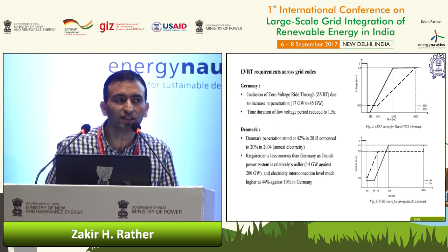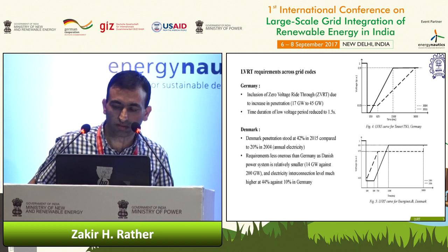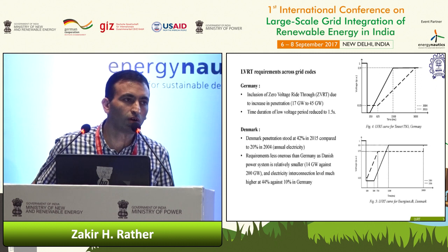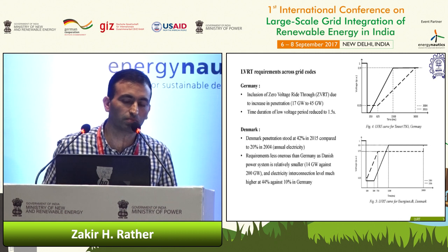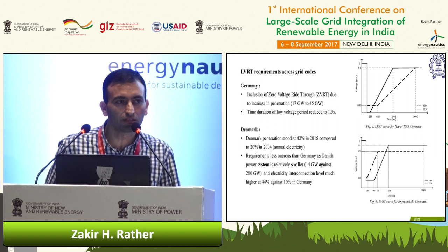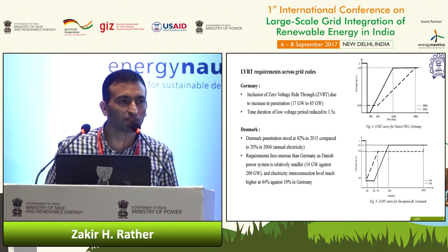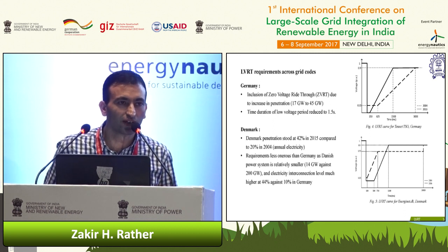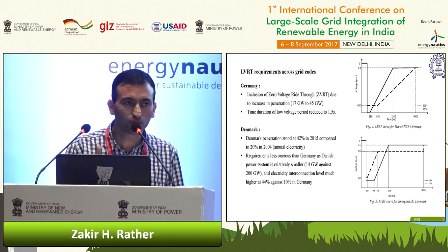The reason primarily is that in the previous years, around 2000, 2003, there was significant penetration of type 1 and type 2 induction generator based wind turbines, and these were leading to a weak grid, because an induction generator will draw heavy reactive current from the system during a fault, during a voltage dip. So that was the reason the system was expected to have slow recovery.